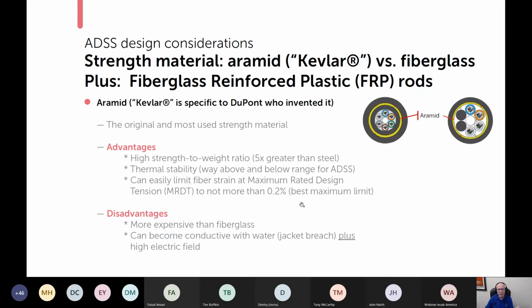It comes from research that Corning did in the late 80s, early 90s time frame. And basically they said, if you're going to allow strain on your fiber, this is what you should keep it to, to have an acceptably low risk of failure.